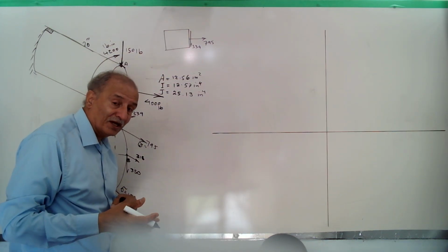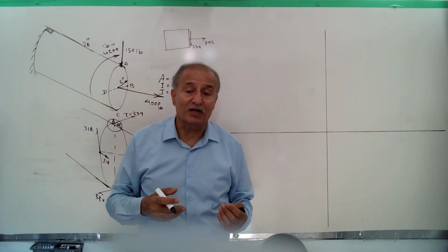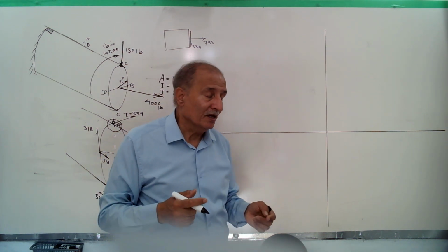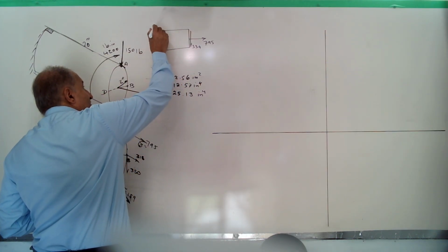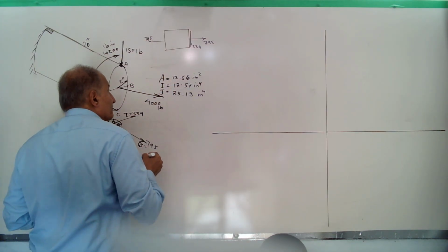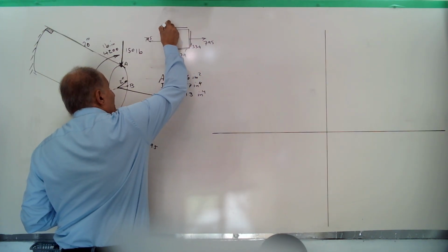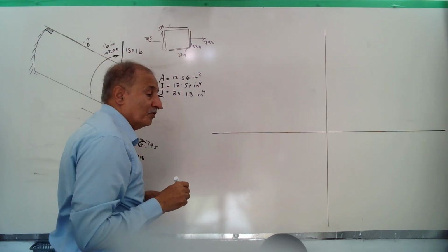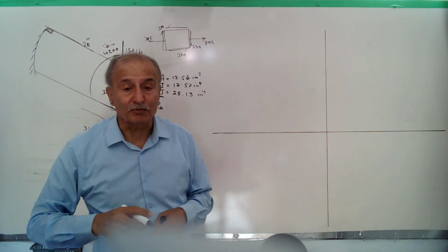For Mohr circle, these two stresses produce a point on the Mohr circle which is called point A. In most textbooks, they call it point A. And because this element is in static equilibrium, we have a certain horizontal shear stress, the same here. There is no normal stress acting in y direction. This is what we calculated. There is no sigma y here.